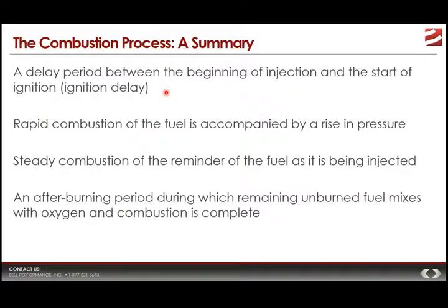The fuel then continues to be injected because all of this is happening at the beginning of the injection process, because remember, it's happening really, really fast. So you get steady combustion of the remainder of the fuel as it's being injected, and then you have an after-burning period where the remaining unburned fuel from that injection stroke mixes with oxygen, and combustion is complete.